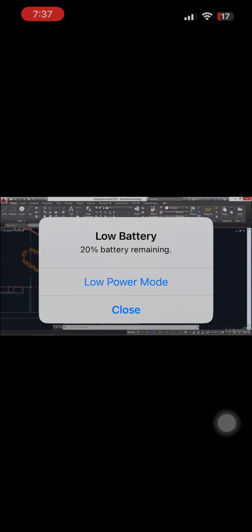Like the rotate command, the scale command also uses a base point which is significant. Let's say we want to scale this coffee table up by a factor of 150%. Let's use the scale tool, which is located right here. Select the table, press Enter, and specify the base point. I'll click a point arbitrarily, sort of down here. And as I move the cursor, you can see what's happening. The table is scaling up or down, depending on how I move the cursor, relative to that base point.